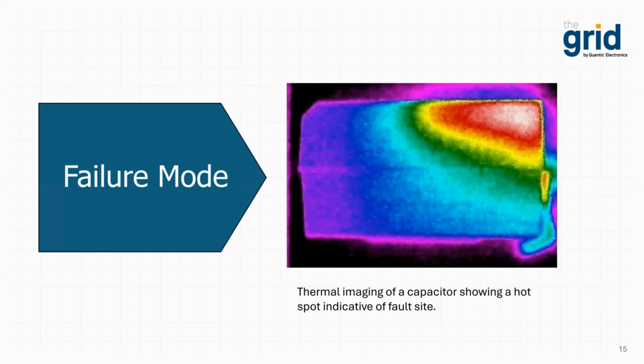Other capacitors can swell either as a failure mode or even as they simply approach the end of their life. This can and will impact other components and subsystems around it and could render the entire vehicle useless. A designer must understand how the capacitor fails to account for this in their design.